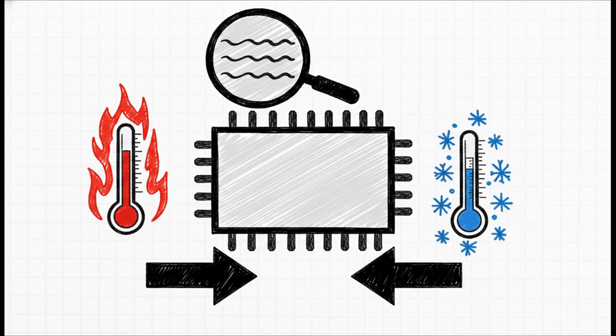Then there's shallow trench isolation, STI, which physically compresses the silicon. This mechanical stress fundamentally alters transistor mobility depending on how close the device is to the trench. You've also got the length of diffusion, or LOD effect, which alters device behavior based on diffusion spacing. And of course, IR drop, where the voltage reaching one device differs just because of parasitic routing resistance. Every single one of these effects is actively fighting against your mirror's precision.